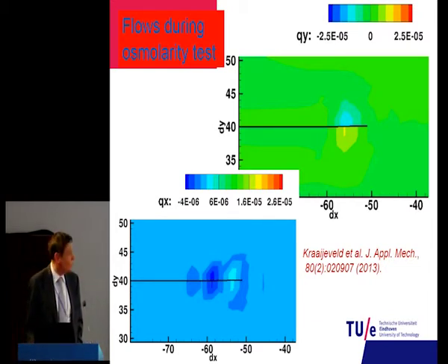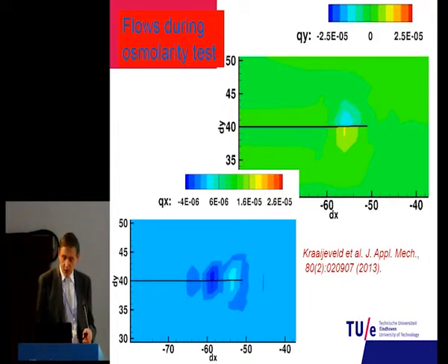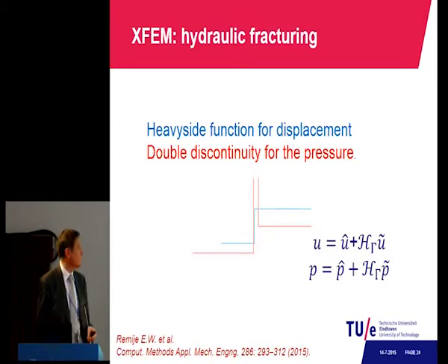We use a cohesive zone as a fracture model, and then we get results which relate to fluid flow: flow in the x direction, flow in the y direction, and the chemical potential. We can simulate propagation of cracks within a poroelastic medium, and in this case I think no swelling was included. Now we found also there a stepwise progression, and we've been doing experiments.